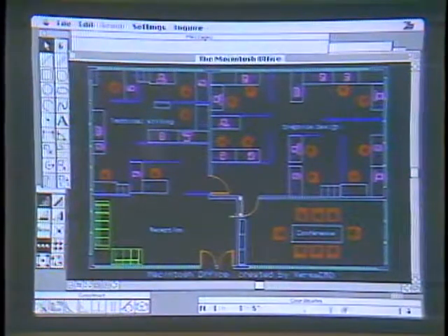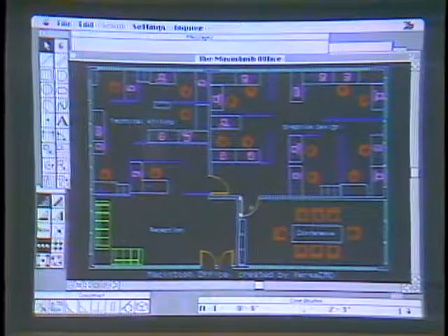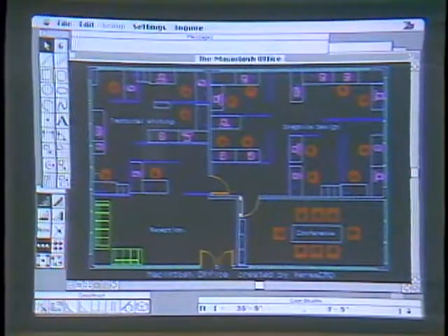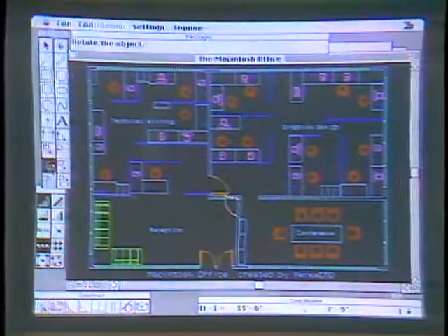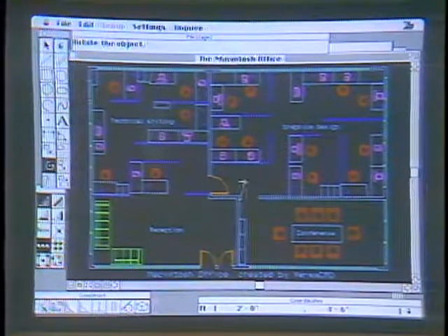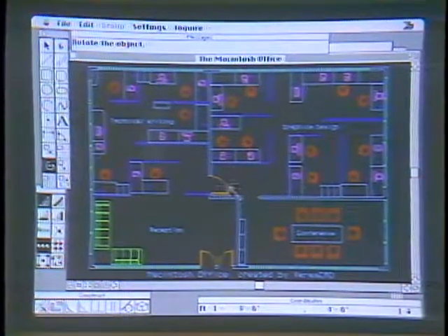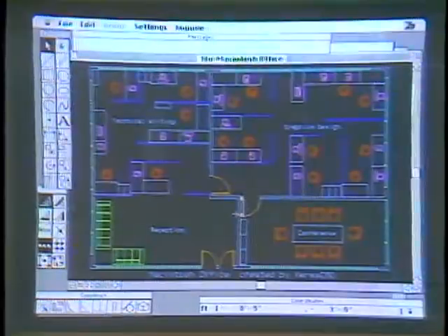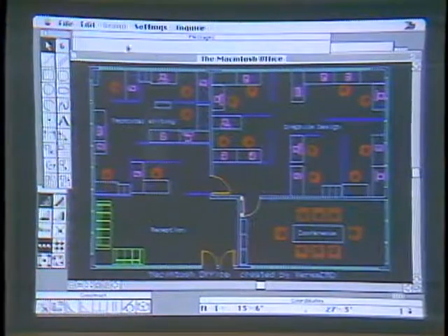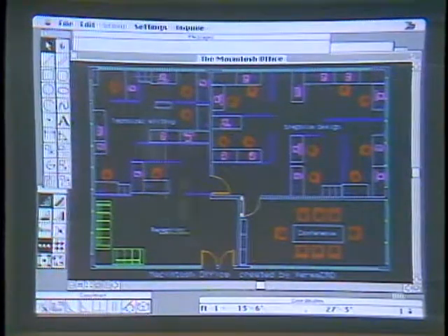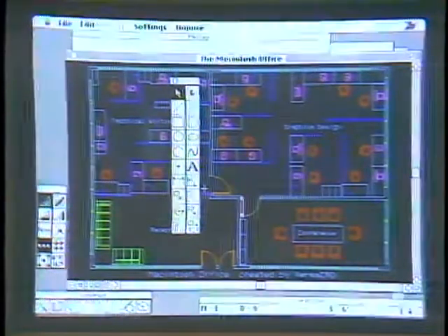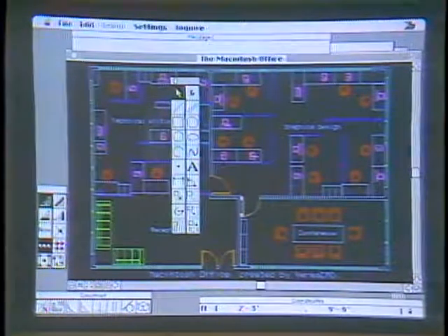As we go throughout the drawing, there are many ways of working with a given drawing. In this case, I'm simply going to take a door and see if two doors collide. So as I go into the drawing and ask for the rotate command, notice that the door can be quickly seen, and you see two doors will be bumping if I put it there. At any given time, I can escape out of my command, so anything you do, you can undo. And I think it's important to realize that these symbols are all being tracked, and a very fundamental part of the software is that the entire palettes on the screen are able to be implemented and used just like people would move tools on their desk.